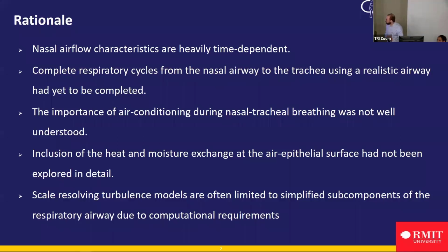So the rationale for the study: nasal airflow characteristics are heavily time dependent. However, the bulk of respiratory simulation studies are restricted to time independent simulations, so running steady state. This is most likely a result of the computational resource availability at the time of the study. However, computational availability has become a lot more accessible, and we have turbulence models that can actually reduce the computational